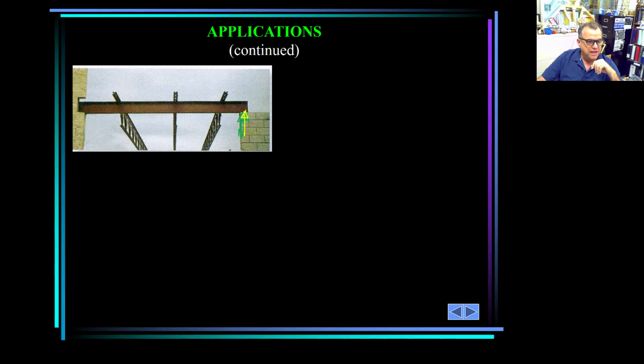Something like that is holding the beam there, but at the same time this other end is also held at this point, and somehow it is restrained, because if I push it in this direction to the left, it is going to be held in that way. And these 3 beams, or truss beams, that are just resting on top of that, will be producing a load here, and another load at that point. And that, with the dimensions and the values of the forces, will give us what the free body diagram of that structure is.